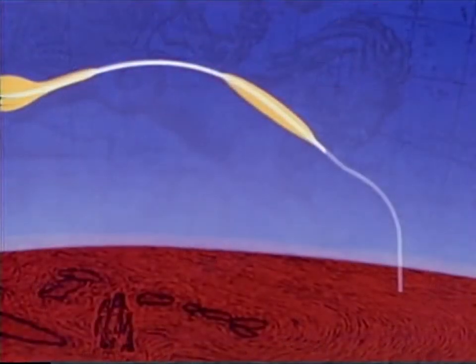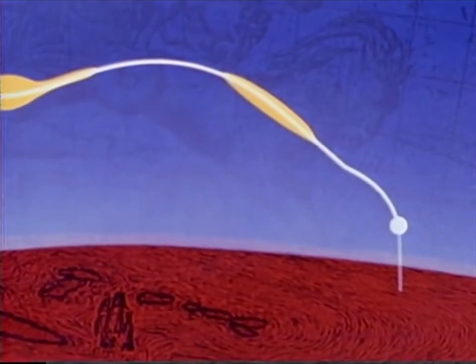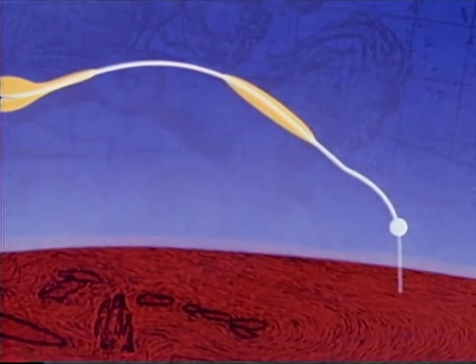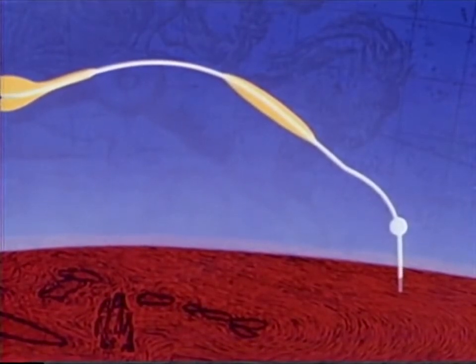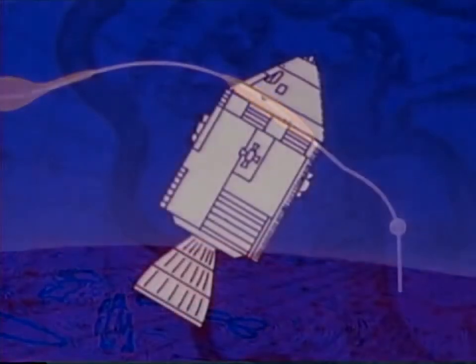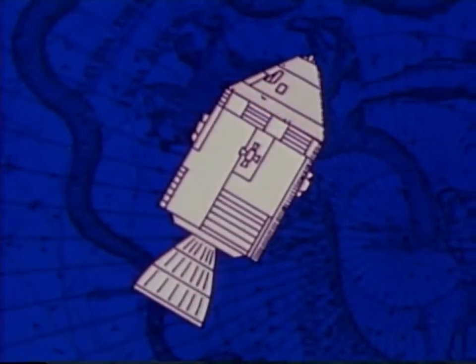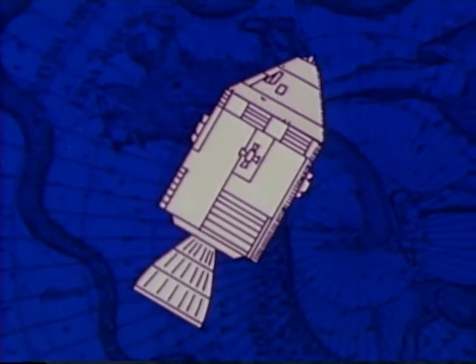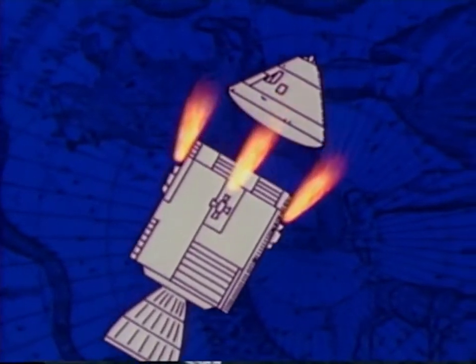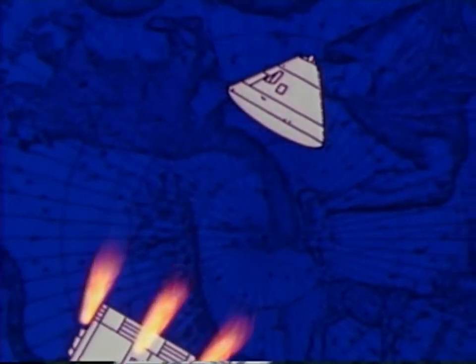The Apollo entry phase will terminate at about 23,500 feet altitude. At this altitude, the drogue chutes will come out, and the spacecraft will descend to splashdown by parachute. Reviewing now, we see that before entering the atmosphere, the service module containing all but the entry oxygen and power supplies will be jettisoned, and the command module positioned in its trim alignment. It enters the atmosphere at the 400,000-foot level.